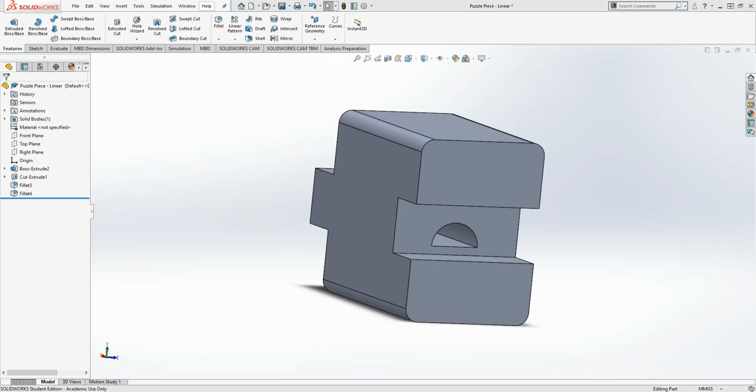Now what it says is we have our contour, but now what we do is we select a surface that we want to extrude to. So it's only going to do cuts up to that surface. If I select a new surface, you can see how the selected area that it's going to cut to changes. So up to surface is a great way of cutting through a surface without having to define everything. You could also do offset from surface too.